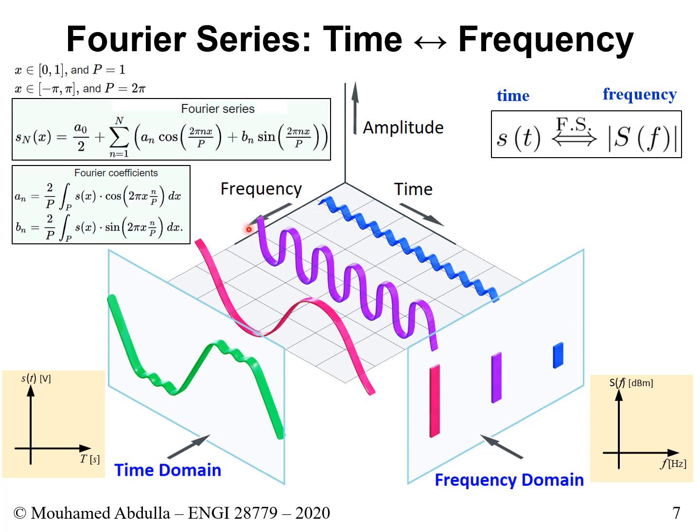And these are the terminologies that we use: second harmonic, third harmonic, and so on and so forth. All of this will depend on the value that you have for your AN and your BN. And AN and BN, like we said before, are values of voltages. What is the voltage contribution at this frequency? So for instance, A3 and B3: what is the voltage contribution of this, and so on and so forth.